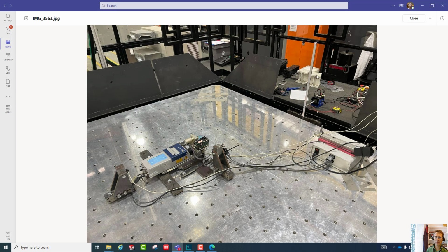So here's my laser vibrometer, modal shaker down here. We've got a force transducer, an accelerometer, and impedance head connected here. The laser beam is currently pointing at the top point on the beam, but it moved down into 6 separate locations. In fact, we started for run 1 at the bottom.